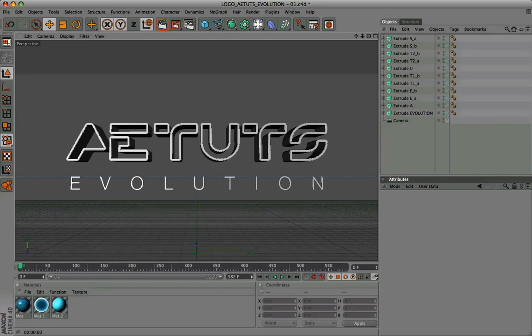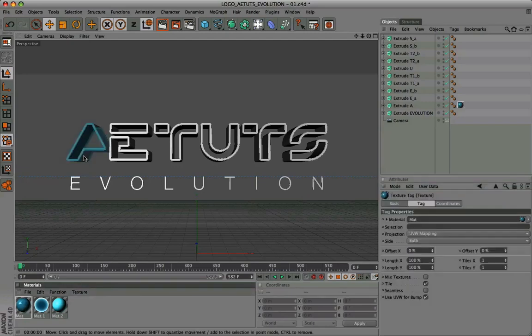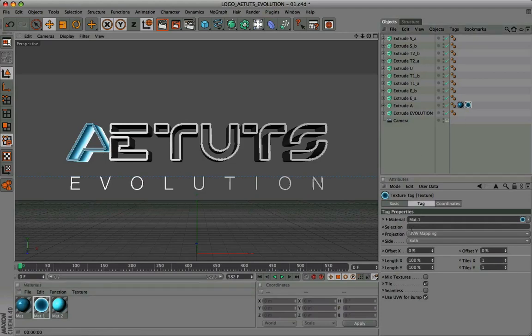Once created the three materials, we can apply these to the extrusion of all the letters and parts of letters. Again, we apply one, then repeat the operation on all the other extruded letters. Then insert the first material on the letter A. Immediately after, drag the second material, always on the same letter. Selecting the second material, on the selection line, write C1, so the second material will be added only in front caps.